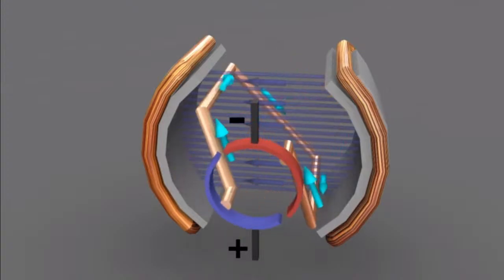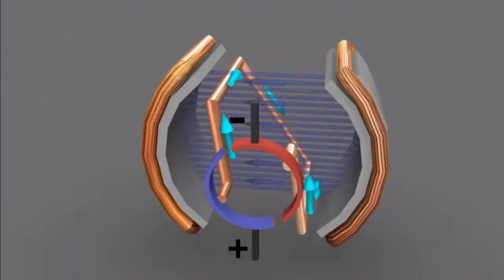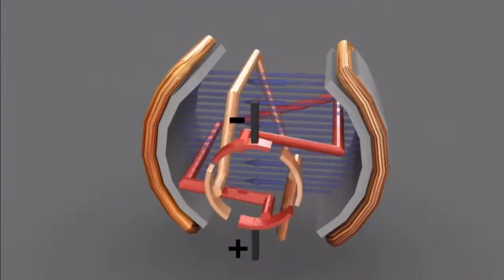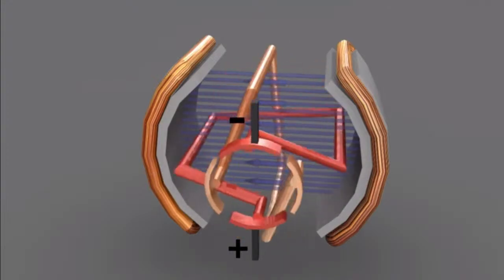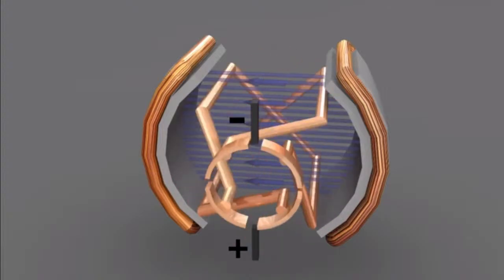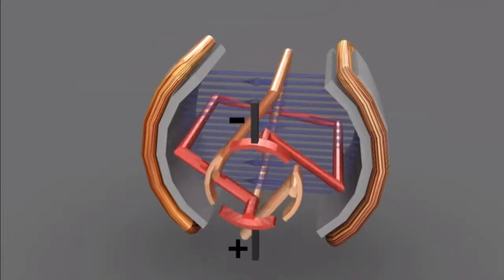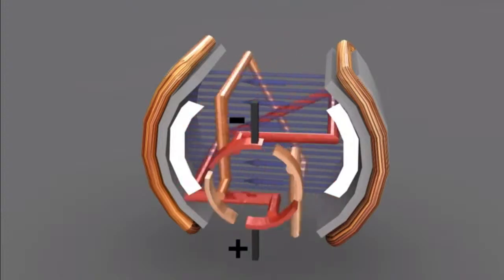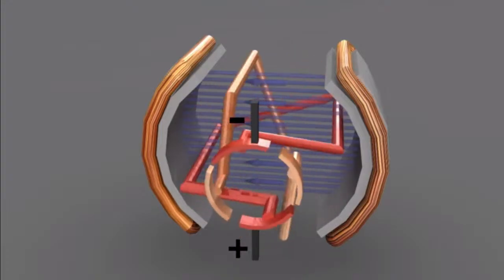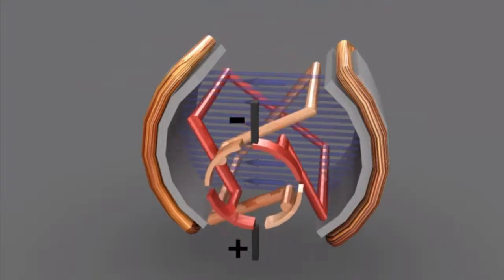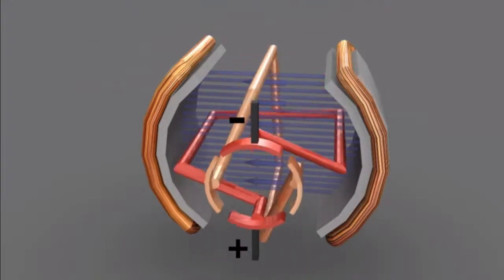To make maximum torque always available at the shaft of the rotor, more such sets of coils with a pair of commutator segments are placed in the rotor. When one coil passes through the region of maximum torque, the next coil will take its place. This way, the shaft of the rotor always provides higher and smooth torque.